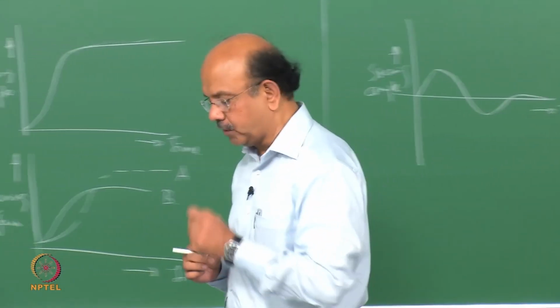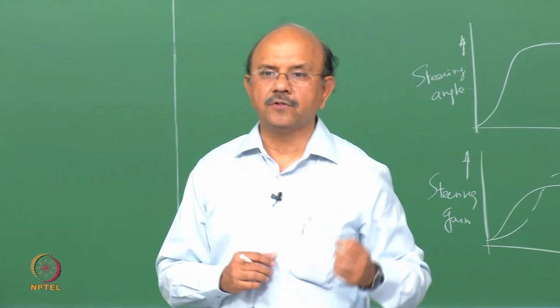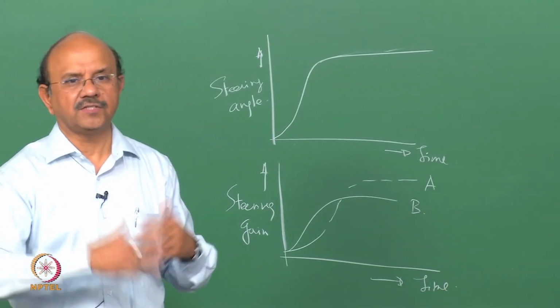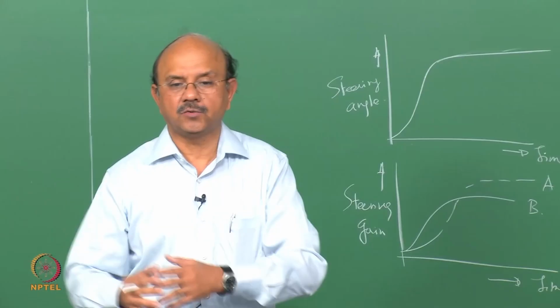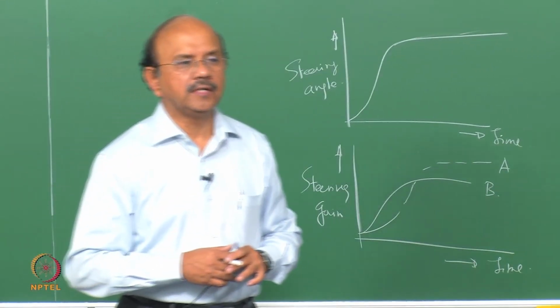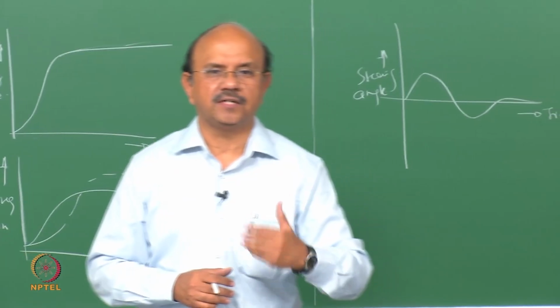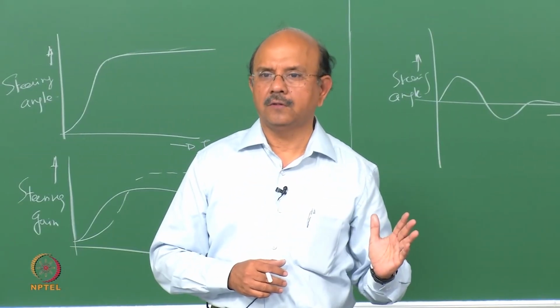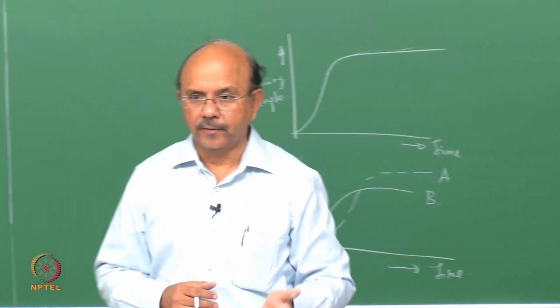We already talked about transient oversteer and transient understeer. Remember that when I'm going to take a turn, I'm in a transient situation, and whatever analysis we had done with respect to K was on steady state. So transient oversteer and transient understeer is when I enter a turn, when I power on or power off, or accelerate. In other words, I accelerate or brake and so on.